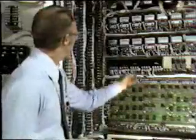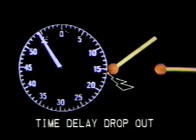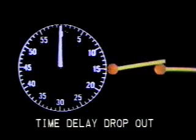The second type of relay is the time delay dropout relay. Contacts on this relay transfer when the relay is energized and retransfer at the end of the timed period. An example of the time delay dropout relay is KT220, the post-lube timer. KT220 is energized when the engine starts and transfers its contacts. When the engine shuts down, the timer is de-energized and begins timing a 55-minute time period. At the end of this time period, the relay retransfers its contacts, causing the post-lube pump to shut down.